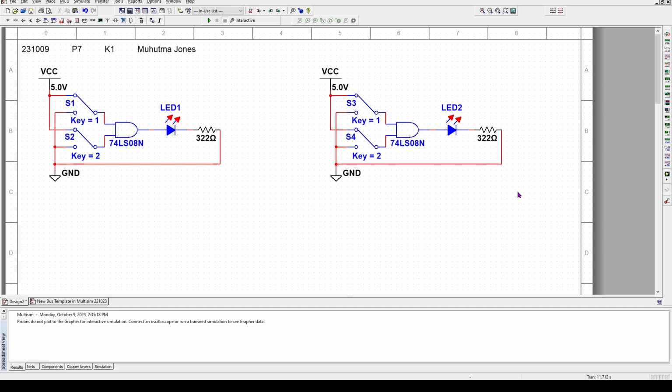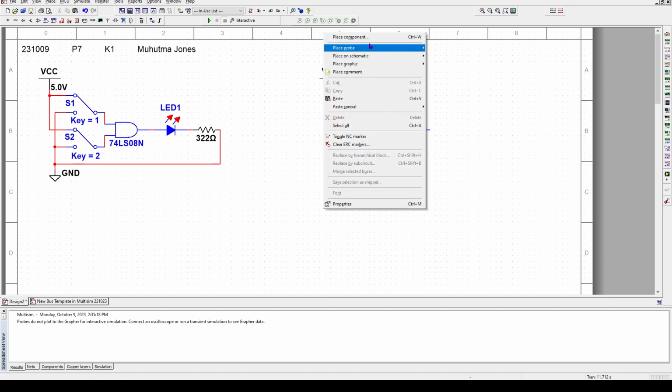In any case, what I want to do now is delete the LED and delete the resistor, which automatically deletes the ground wire. Even though on a real circuit, if we were to put this on a breadboard, we would actually have to use an LED and a resistor on the breadboard, and the output of the resistor would have to be led back through a net wire back to ground so it would work. But there's a shortcut that cleans this all up quite well, and that is something called a probe.